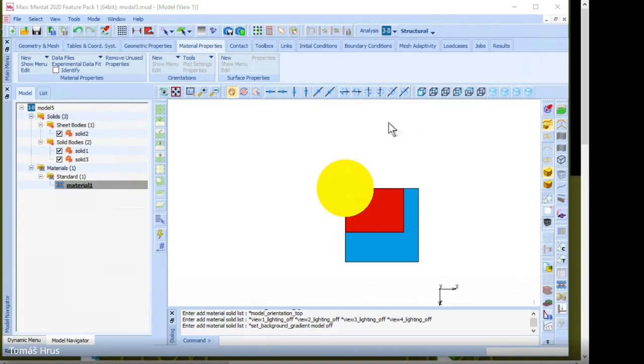Then the second quarter, this part, and the second half, this one, is deformed in the same way as this quarter. So it's not necessary to solve the deformations and the stress on the rest of the model, because it's the same, only symmetric. So it's very useful to use the symmetry and solve only a small part of the body, because the rest is nothing interesting.